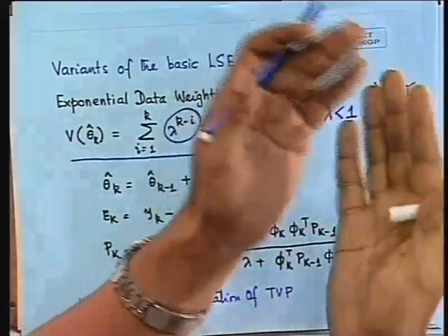So by the fact that you are calling it a parameter, even if it is varying, its variations must be much slower than the signals which you are calling states, right? Therefore, generally parameter variations are much slower compared to your sampling instance. They will probably vary by 10% over maybe 500 samples.